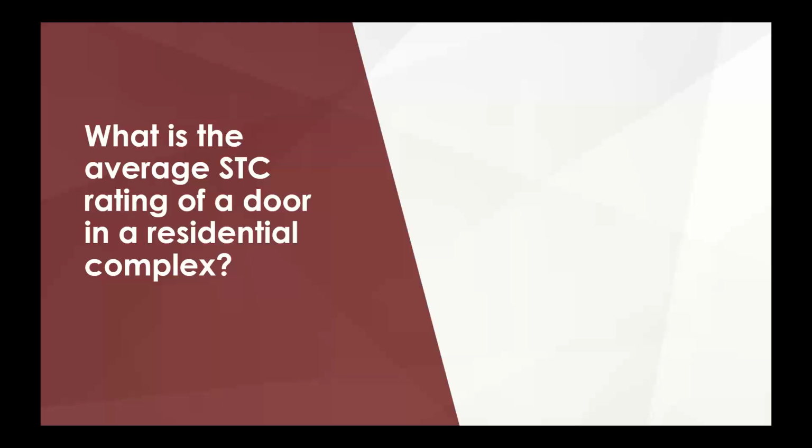All right, before I go into this one, I'm going to ask this question: what is the average STC rating on a door in residential? The reason I'm asking is I got invited out to a job site to meet with the drywall contractor and the sound consultant, and just to hear them out on some of the requirements. The drywall contractor said to the third-party consultant, hey, you recommended this sound report, 25 gauge studs, 24 inch on center, but I've got to tell you, when I get to my doors, I have to do a double 20 gauge stud for my king studs on there. Can I do that?